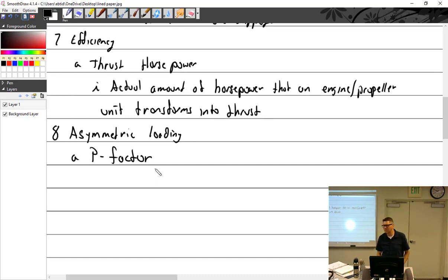What I'm talking about is the zero reference angle, and that's one of the things you're going to do when you adjust the ground adjustable propeller that we have, and it is sitting at an angle. So you have to take that into consideration. With the protractor, you have to figure out what is zero, what is neutral. There's really only one thing on the engine that is absolutely zero, perpendicular to the hub of the prop, which is the crankshaft.